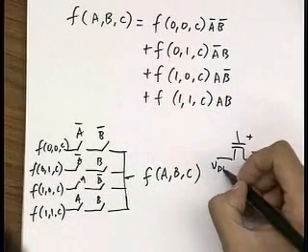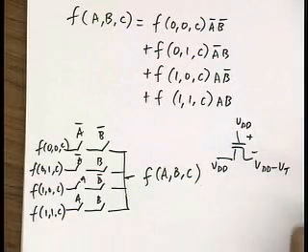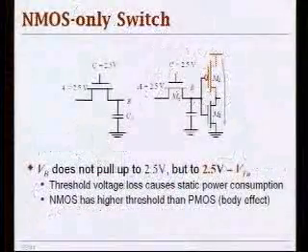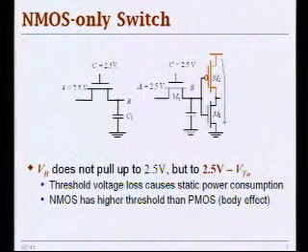If you have VDD here, then you always have VDD minus VT here, okay, to maintain the channel there. Now, if you look at the slides, can we switch here? Okay, good. We see that this is not really that bad. The bad thing is that when it drives inverters or static CMOS gates, what happens?